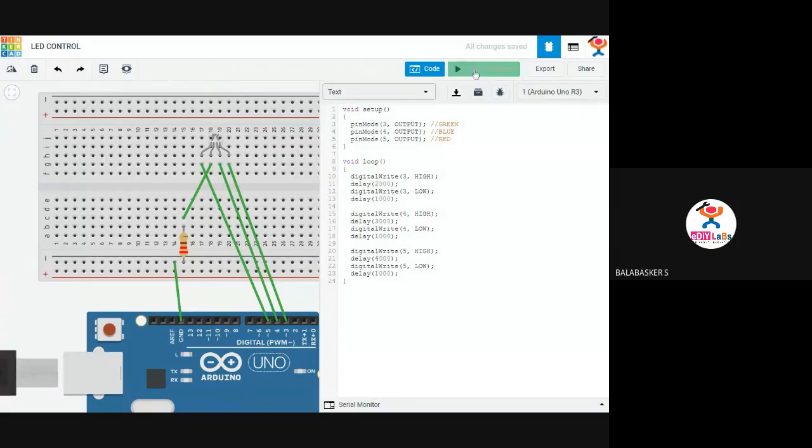Okay then. So this is all about the thing. As I have already said, we are going to use multiple tags. In the tags, pin mode is used for declaring the pins, the purpose, whether it is input or output, that has to be declared. And digital write is used for writing a value from the controller to any external device. And your next tag is delay. Your delay is used to control the time difference between one execution and the next. These functions are readily available. We are just calling the function and providing the value. The task has been completed.